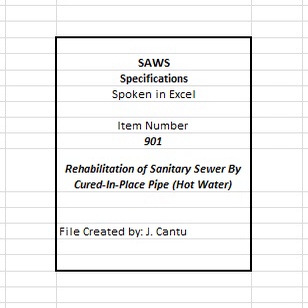D. Separations of liner seams in the finished liner pipe are unacceptable and shall be removed and replaced by the contractor at no additional cost to the owner. 1. If a separation of a liner seam exists, the contractor shall repair or replace that section of the pipe at no additional cost to the owner. 2. Methods of repair shall be proposed by the contractor and submitted to the engineer for approval.